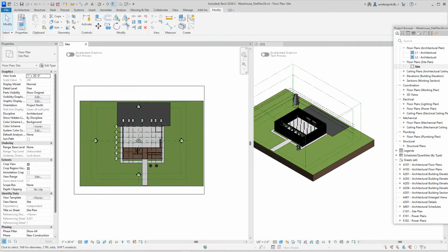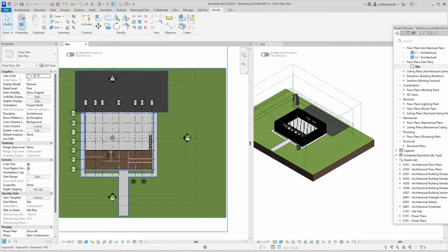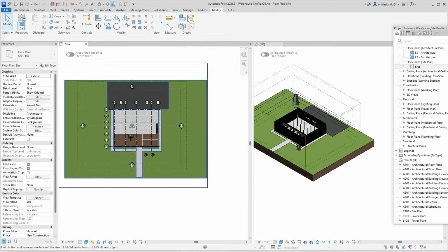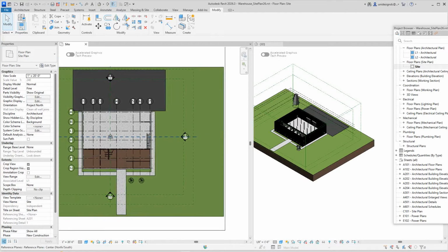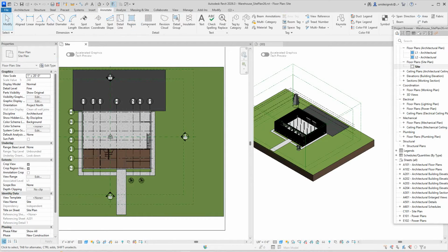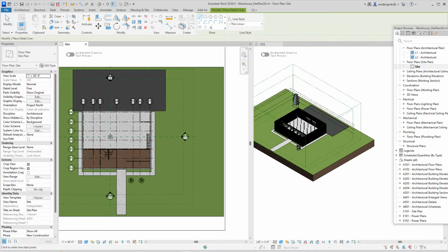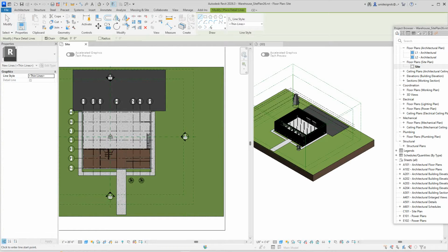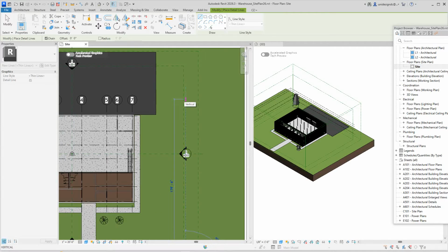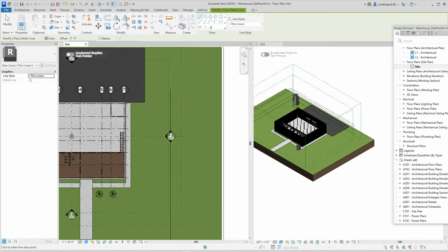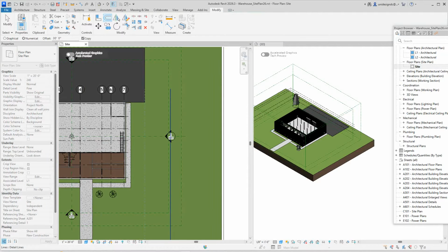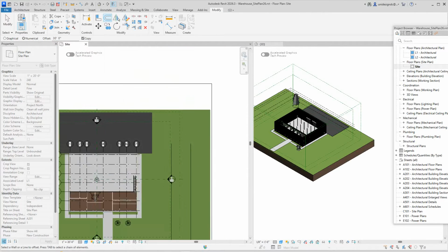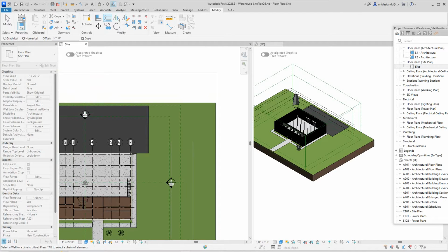Now, if you wanted to do a road or something in here, you'd probably want to come in this way. So what you can do is go into the Annotate tab and go to Detail Line, and we'll push a road, we'll go line here. Take it up to there, I think. And we'll offset this about 30 feet, whatever. Say 30 feet away here, go that way. And then I want to do an arc here.